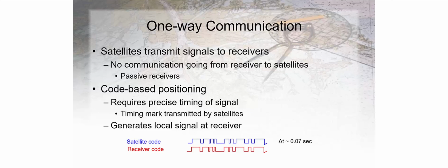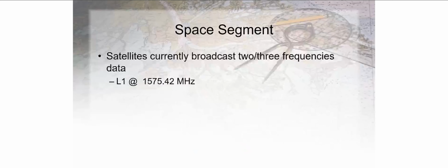We haven't heard the satellite's signal yet, so once we hear it, we match it up with our code that we generated with our receiver. And then by doing that, we can actually see the precise time that it actually took to transmit that signal, which tells us how far away our satellites are. And if we know the position, that's what the ephemeris data is for. If we know the position of the satellite, we know the control coordinates of our satellite, and therefore we know with the time difference, we know actually our range to the satellite.